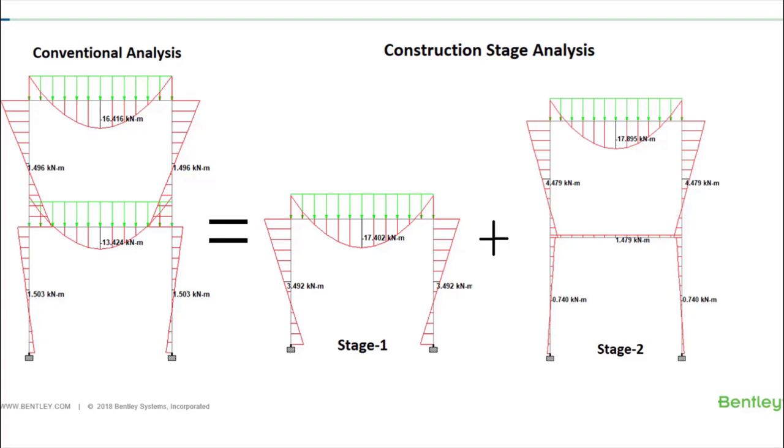In the real life scenario, once the construction of a floor level is over, it is exposed for a certain period, and on top of that, loading from the story above is transferred through different types of props and shoring to the lower floor levels. Due to this, the lower floor undergoes certain geometrical changes and load path changes.